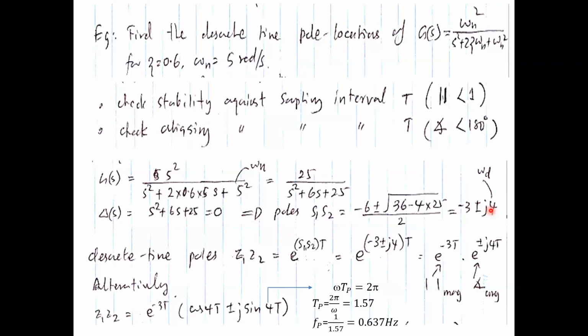Now, the problem is very clear. You have a varying signal, sinusoidal waveform, with 4 radians per second angular speed. And for the moment, you can forget about the damping, the decay. This -3 decay, of course, decays the amplitude of the waveform, but that's a separate issue. So you are dealing with a 4 radians per second signal, and you have to tell me what is the minimum sampling rate for this waveform. Can anybody guess?